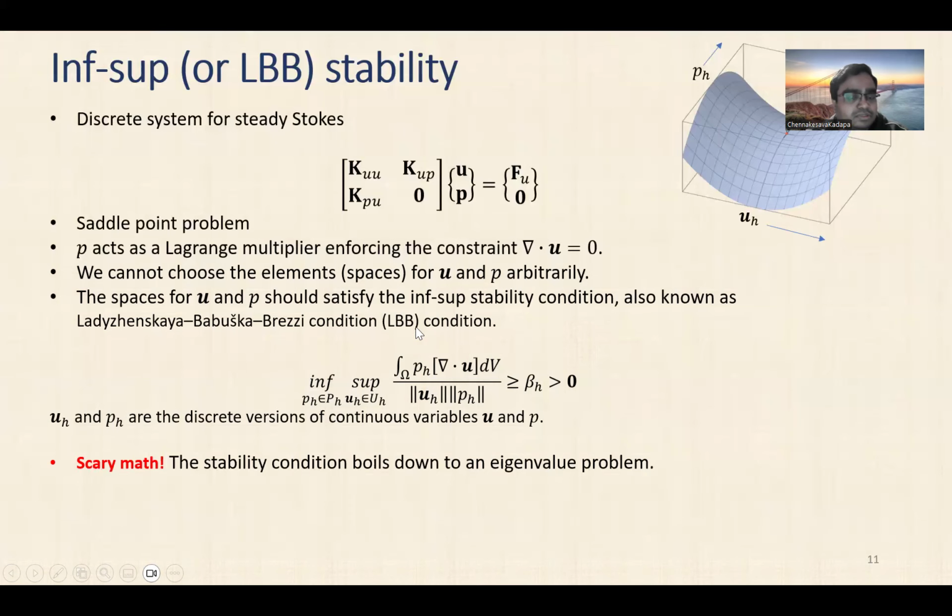Right, that's the theory. If you want to keep this as it is without adding the stabilization, the zero block remains. When we add the stabilization, this zero will disappear, and we have a non-zero block here. So we can solve it, and we get a stable solution, that is pressure and velocity fields without spurious oscillations. But the alternative is to use LBB stable elements.